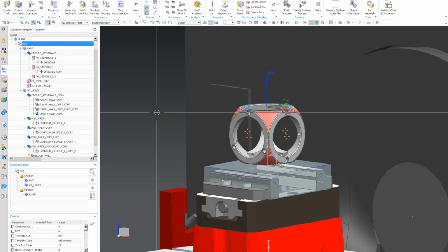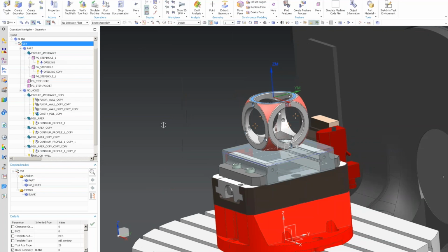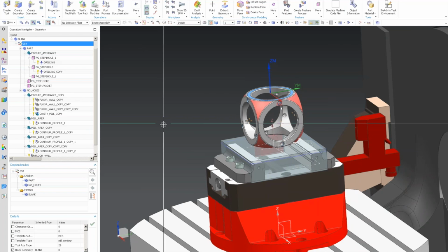We're doing all 800 holes in one toolpath, one operation, and using tool center point to transfer between them. But I need to come up with a non-proprietary mold to show, and I'm almost done with that, and I can certainly present that in another webinar.